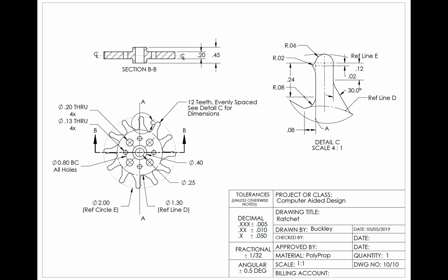You can never do anything but that. In this type of part, it can be conveyed pretty clearly from the front view that this is just going to have a little thickness to it. So an isometric wouldn't tell us much more than the front view and the section view together. And I'm going to use the space that I normally would have held for the isometric for my detailed view. So this would be a legit way to do this.